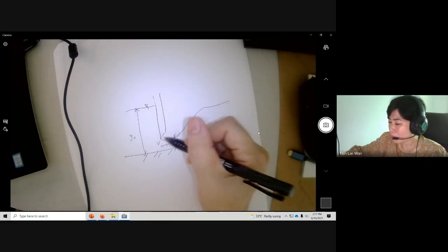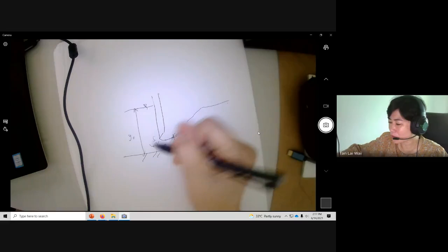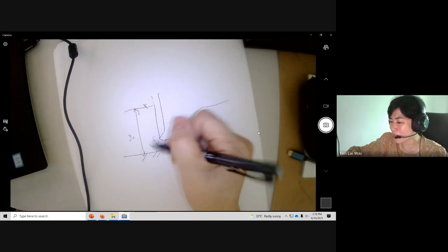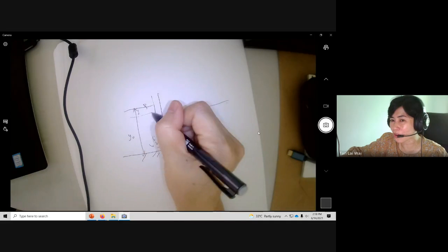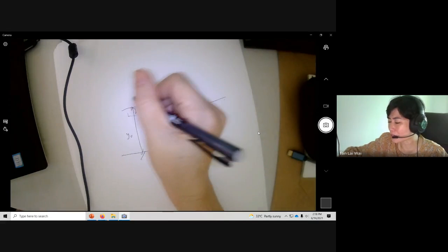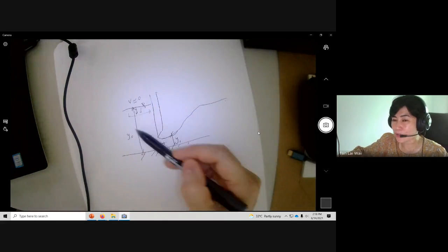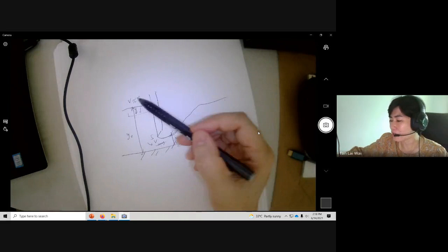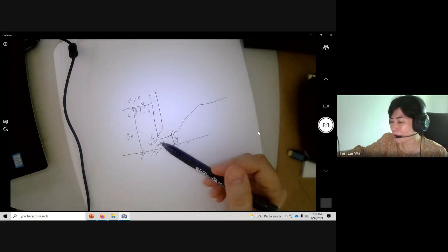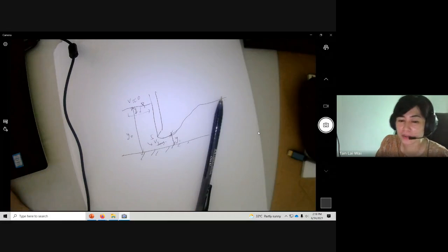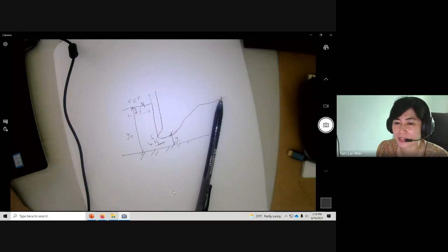When this comes out, you would notice that the velocity at this point is going downwards, because it's not going horizontally. The velocity is very small because you have a huge upstream storage, so the velocity is 0. Therefore, you can assume this as 0 compared to the velocity coming out from the orifice, the rectangular orifice or the opening of the sluice gate.